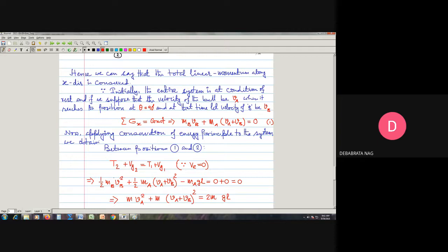So we can say T2 is going to be the total kinetic energy of the system, since we have two particles here. Assuming that the trolley is a particle, the bob of the pendulum is another particle. So we just apply the principle of energy. That means actually this here represents summation. That means we should have put this sigma sign here in front of it, sigma. And here as well we need to put this. So let us better write this sigma sign, because this is going to be applicable.